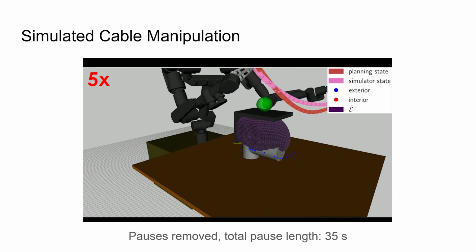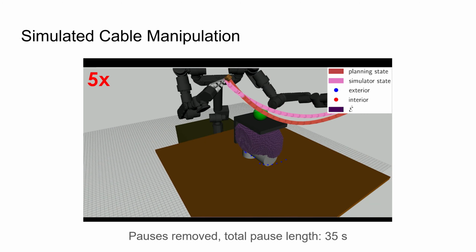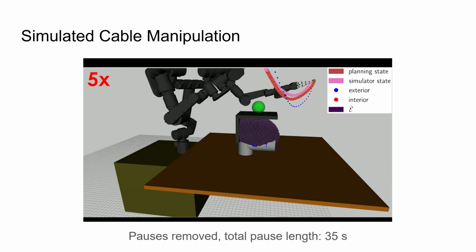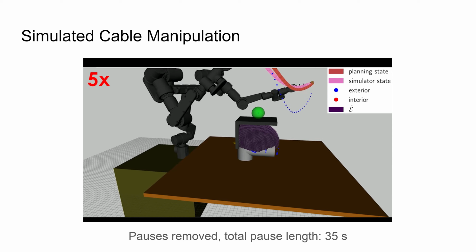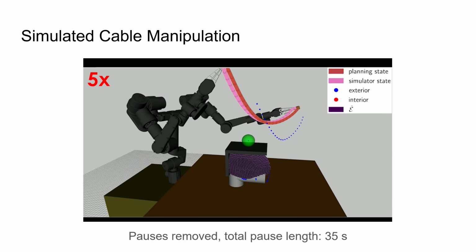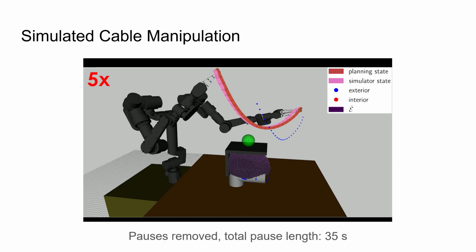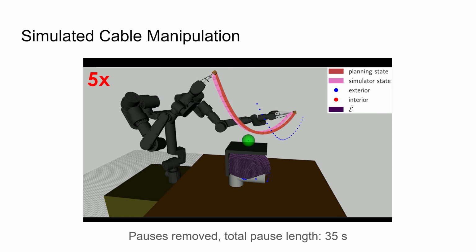Data are added to the GPIS when contact is estimated or if a local minimum in the cost function is detected through low motion of the cable. As we use the uncertainty in the GPIS prediction in our cost, adding the local minimum alters the cost landscape. A local minimum can arise due to the relative balancing of the different cost terms. Altering the exploration cost landscape through adding data offers a simple way to address this issue.